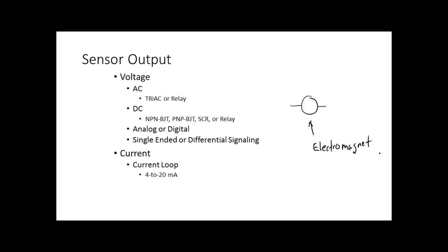But what we do with a triac, well, I can show you all the symbols, but we could draw it as a block too, but this is the symbol for a triac. We bring our AC in here. So this might be AC in, and this right here might be AC out. And then we put a signal into it right here. And guys, when we call it firing, when we put a signal right here, this would be called the gate. That sucker turns on and lets AC go through. We don't put a gate pulse on there, it turns off.